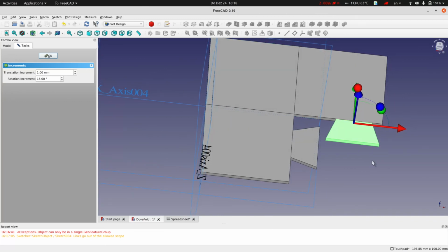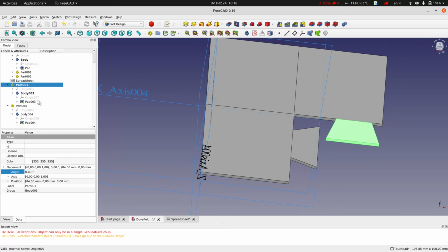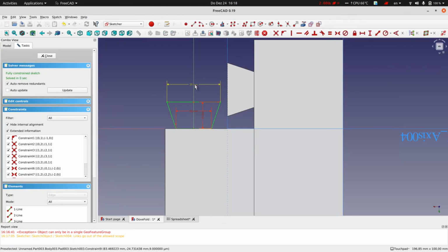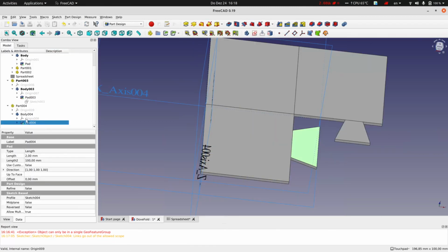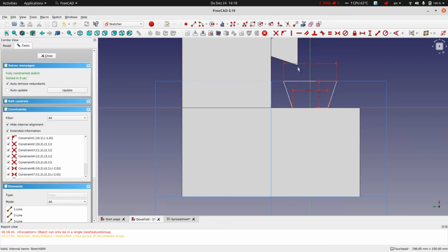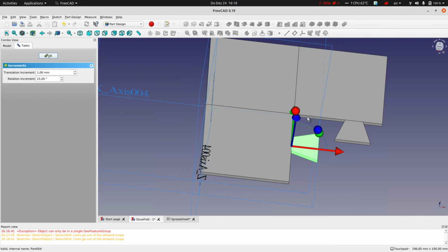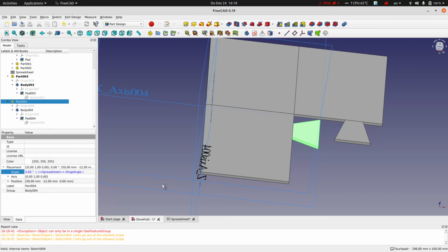Now these are actually going to be too large, aren't they? So let's just, if I'd linked them I wouldn't have to monkey about now. I could change one sketch and they'd both update, but never mind. So call it 20, let's make this one 10. And we're going to do the same thing with this one. 20 and 10. Right. Now let's move the part, I think would be better, so they don't collide. Okay. So let's see what happens now.